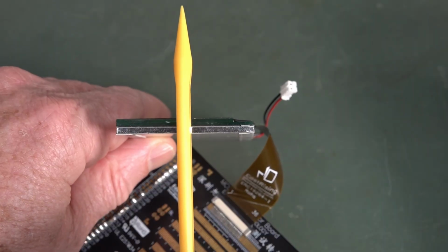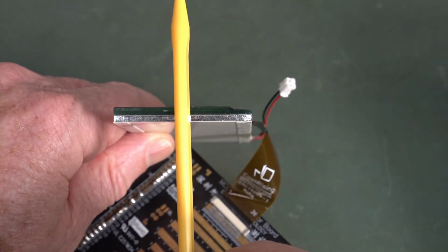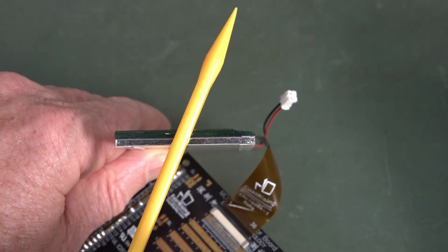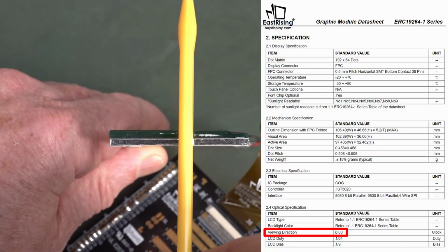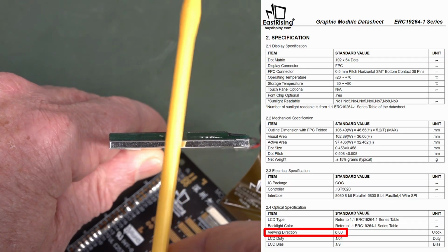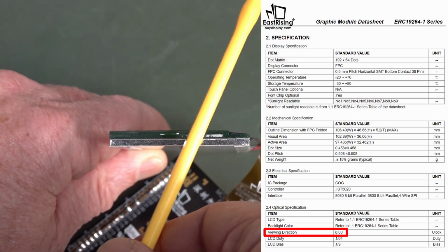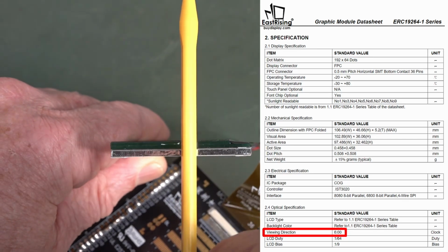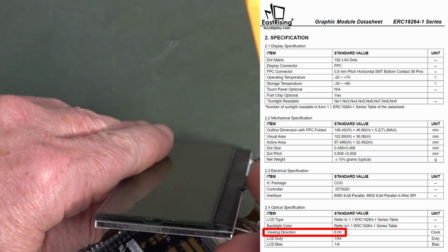So when you order LCDs, either custom or off the shelf like this one, they will have what's called a bias angle or a view position or something like that. The terminology can interchange, but we'll just stick with bias angle. What that means is that you can get them in 2 types, either 6 o'clock or 12 o'clock. It refers to either up or down on a clock, basically. And this one's a 6 o'clock one if you look at the data sheet. What that means is that this is the bottom of the LCD.